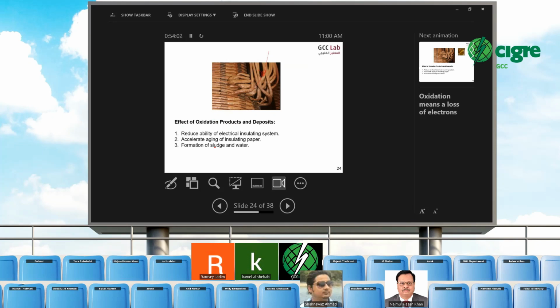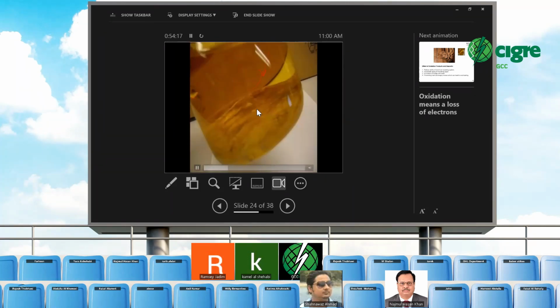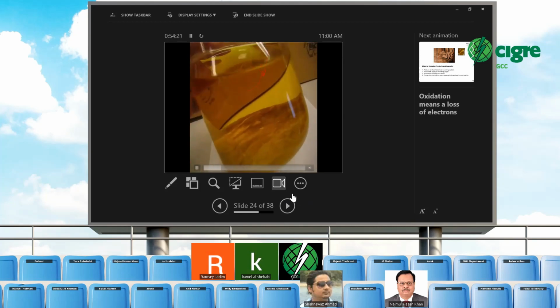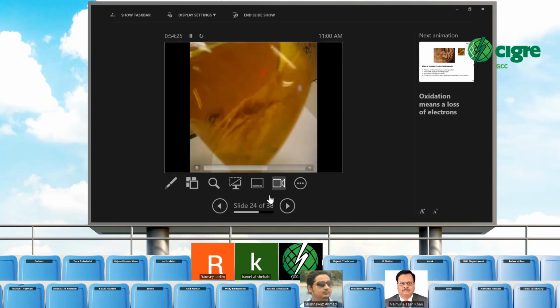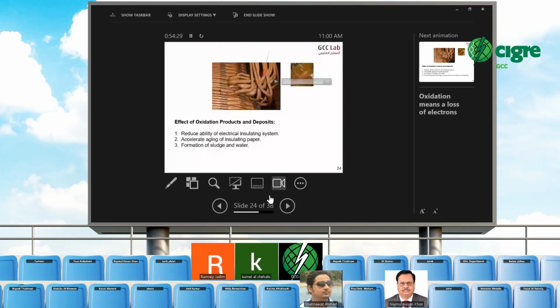And one time I got formation of sludge. One time I got here, I think this video film also, sludge in the oil coming to the lab. If you see the sludge, this one, that means you already have oxidation deposit in your transformer.